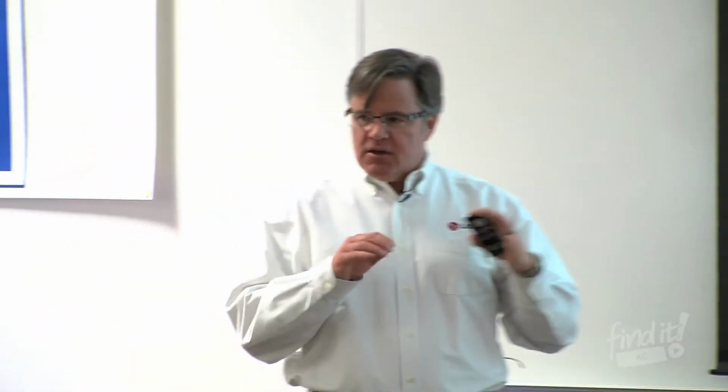So if you're piping in parallel, this is the layout that you would be looking at. A lot of individual boxes feeding a lot of individual spaces. If you can pipe in series, you might have one box like this, maybe another big box that's piped in series. Or if you're doing both styles of piping, then you can branch out and feed the spot. And this is what I'm talking about when I'm saying that as you get into the heat recovery side, that's where different layouts come into play.